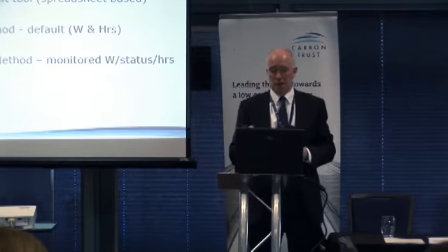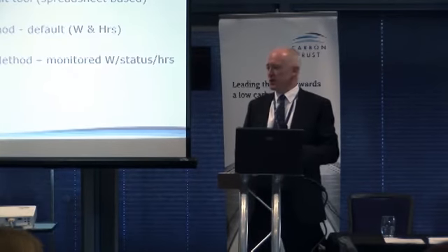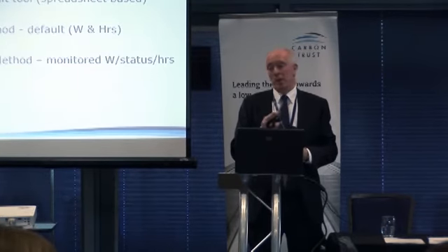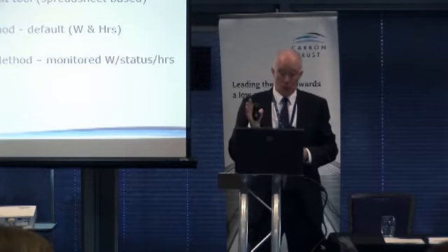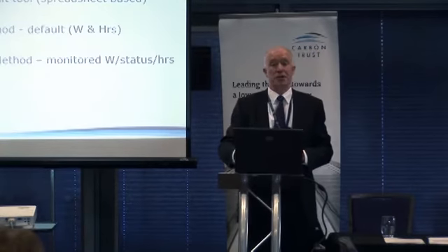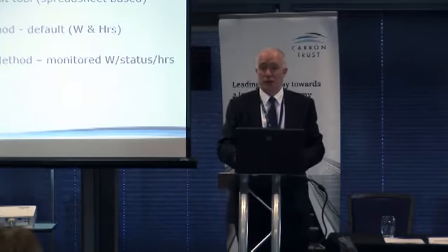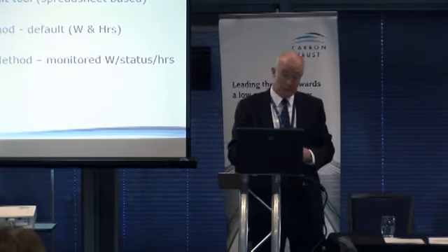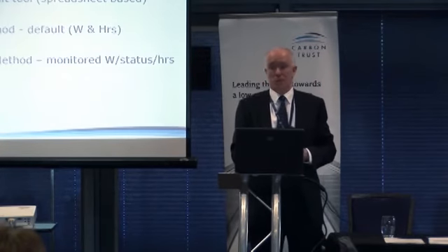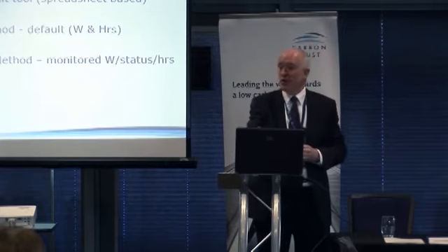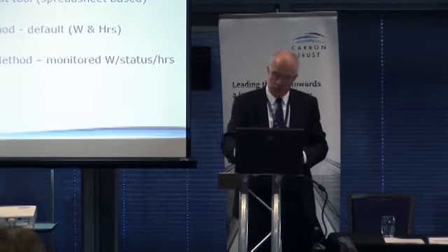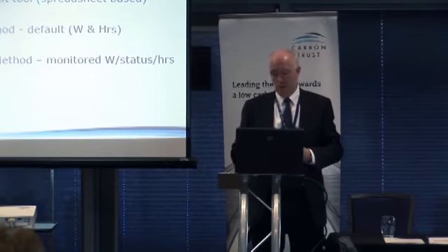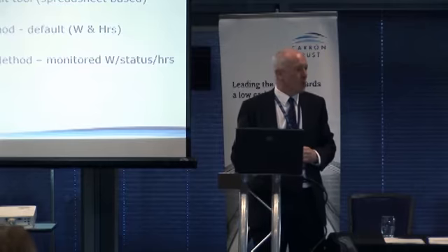And so it's a very, very simple, quick method, and you can get a reasonable, quick audit out very fast by doing that. More accurately, you may want to have an electricity meter, and you might want to monitor a laptop as it works. So this laptop will take about 30 watts as we're actively working. At the moment, it's probably dropping down to more like 20 watts because we're not doing a lot here. We're just PowerPoint projecting. So we've got 10 watts to the screen-ish, and we've got 10 watts to the processor unit. So this will take about 20 watts. So 30 watts when it's working hard, 20 watts when it's sitting like this. Put this into idle mode and it'll be less than 1 watt, something like that.